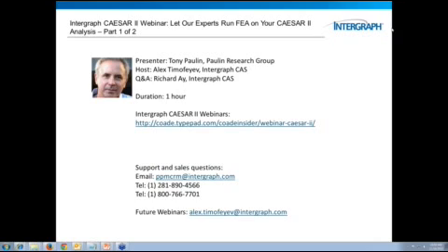Actually, that's one of the reasons, Mandeep, that we asked folks to send models, because there's a whole lot of little reasons why you may need to improve SIF calculations. One of them is that when you have a small d over D intersection, the extra flexibility that the code gives you now really isn't there. So in some cases, intersections become stiffer, but that's reality.